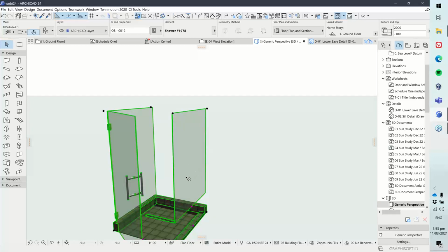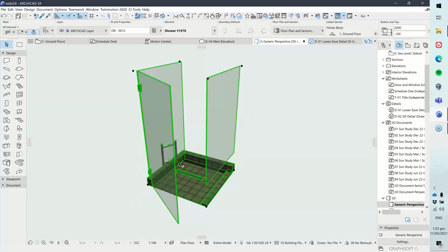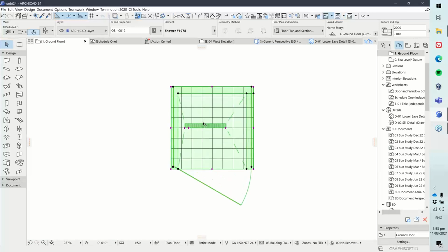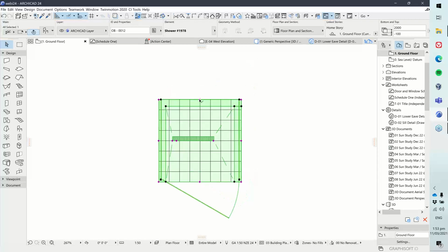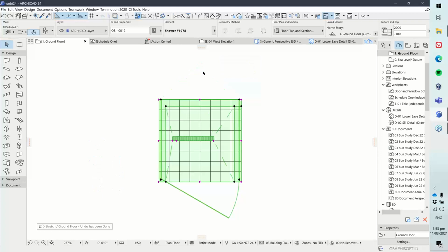So we're going to look at the other editing things that we can do back in our floor plan view so that you can modify the way that works. So just to drop back out to our floor plan view, you can see with it selected at the moment, I've got a bunch of vertexes similar to how I did for the other two cases. And if I click this middle one, it's going to do exactly what you'd expect it to. It's going to make an angled corner inside of it, which no person would probably ever want to do. So I'm just going to undo that.